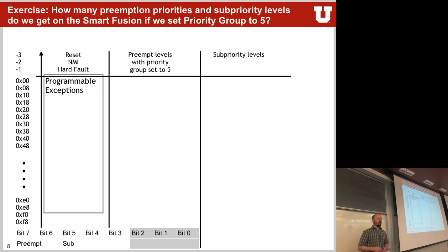Now, let's assume we have 2 different priorities. Actually, these are all of the possible priorities given this bit mask. If you notice here, we are always incrementing by 8, so these 3 bits will always be 0. So we have priority 0, 8, when bit 3 is 1.